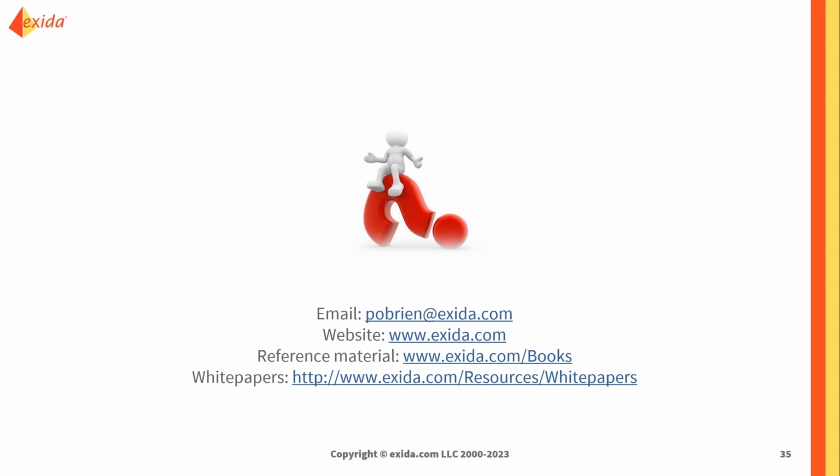61511. So certainly if there's a machinery application where a lot of the safety functions are low demand mode as opposed to high demand mode, it certainly would be very beneficial to fall back to 61508 and look at that in terms of best practices for handling low demand mode. So certainly that's a logical step there.